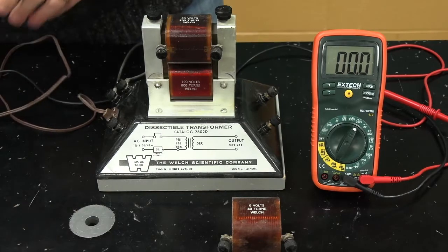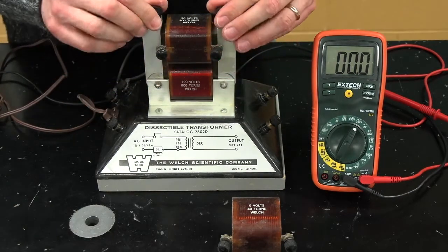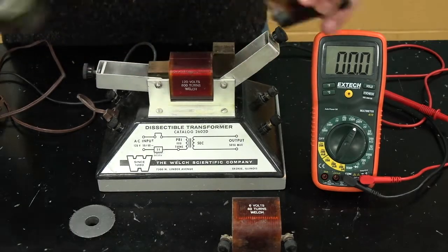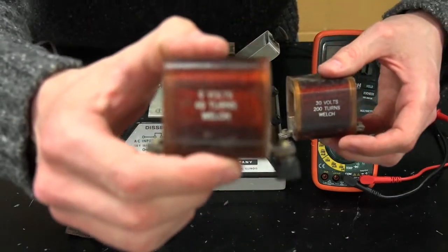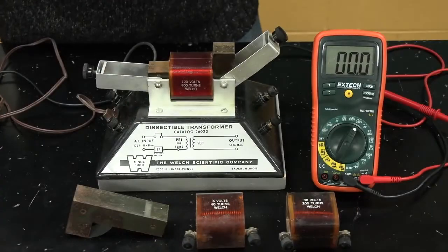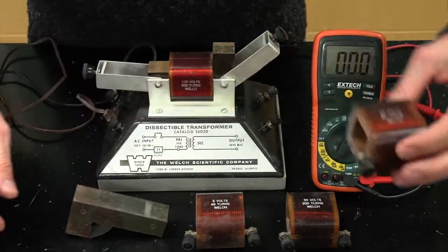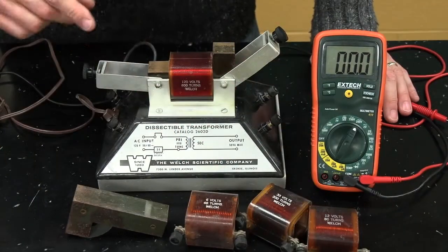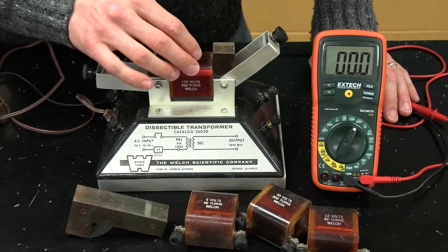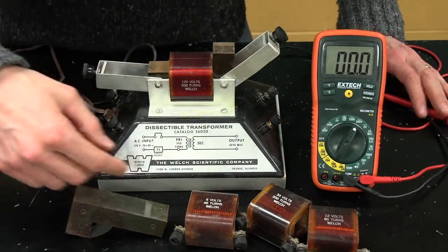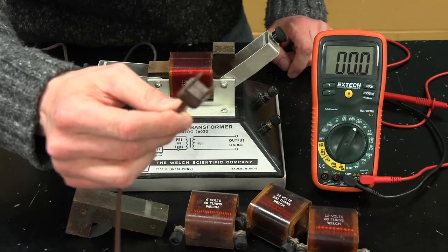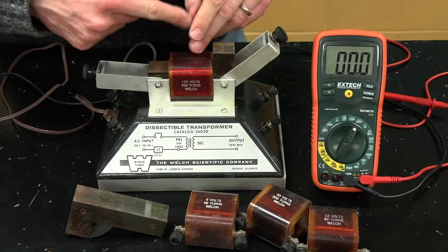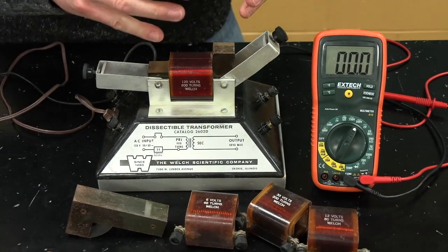Before I go back to the board, I just want to mention that notice all these coils here, they're fewer than 800 turns. I've got 200 turns, I've got 40 turns, and the third one was 80 turns. All less than 800, and all of these give me less voltage. The beauty of alternating current is, what if I wanted more voltage than the 120 volts that comes out of the wall? Instead of 800 turns, maybe I have 8,000 turns up here.